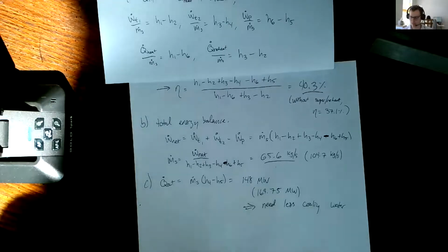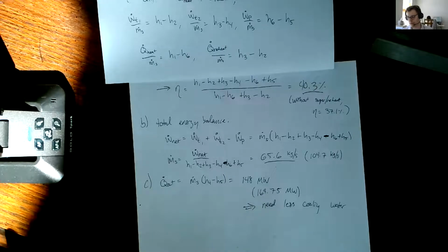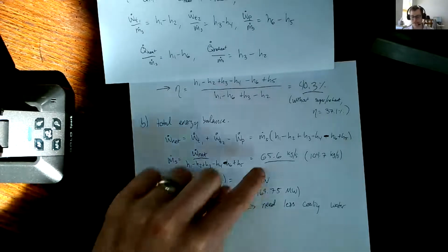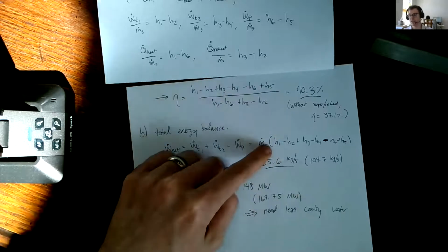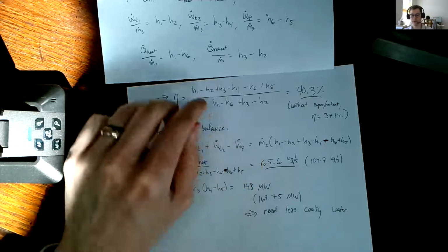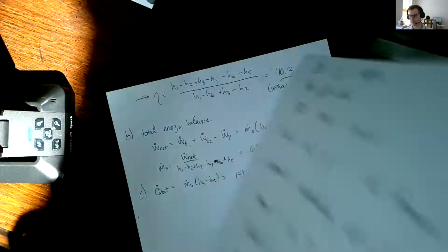So just to close this discussion of superheat and reheat, of course, in reality, all the processes in the turbines and the pump generate some entropy. They're not isentropic, and so the real performance is poorer. Just like we saw going from the ideal Rankine cycle to a cycle where the turbine and the pump had isentropic efficiencies of 85%, we saw the performance degrade. If you did this again to here, you would see the performance degrade again. But it would be much better than it was without the superheat and reheat that we saw in the first example we worked today.